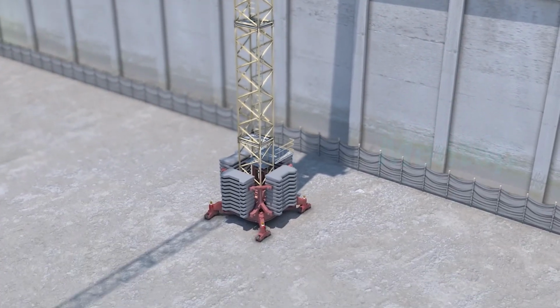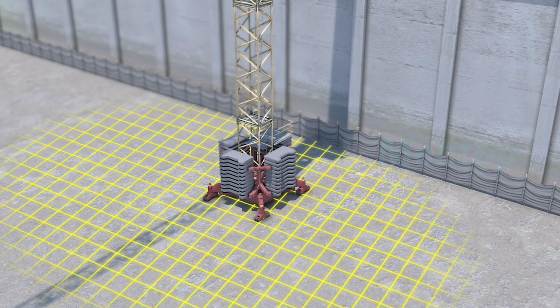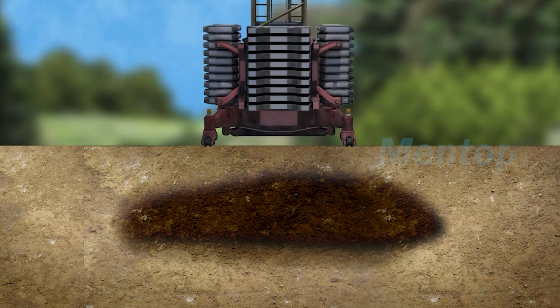Your employer should determine whether the ground is sufficiently level and firm to support the anticipated weight of hoisting equipment and associated loads. There could be unknown hazards underground, such as retention vaults and voids. If a crane or other equipment is placed on top of this area, there is a risk of collapse.